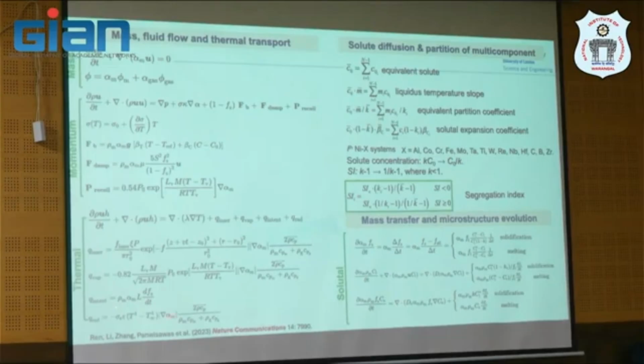Vaporization is some mystery. When I say mystery, it's because it's actually based on the assumption of an ideal gas at the moment. That's the balance at the surface between the liquid metal and the atmosphere, or the gaseous phase. And then we balance the phase there, and we assume that it behaves like an ideal gas, which is not wholly true in the extreme rapid solidification condition. But anyway, that is a working model at the moment. And then radiation and heat have been taken into account in this term. So we use volume of fluid.